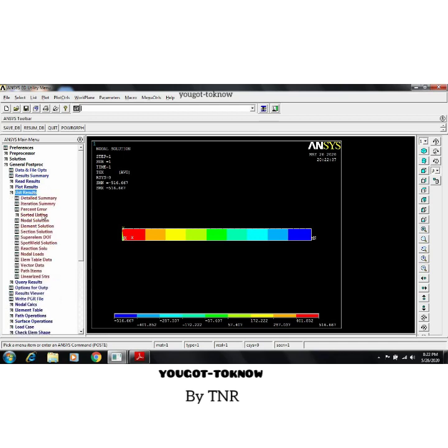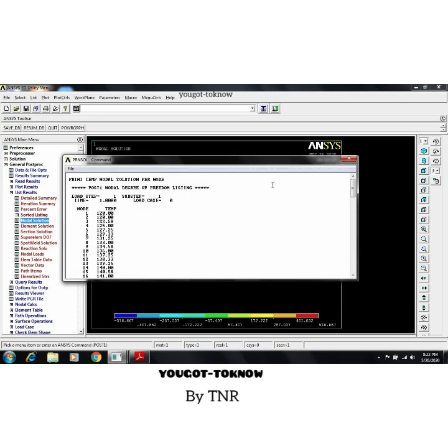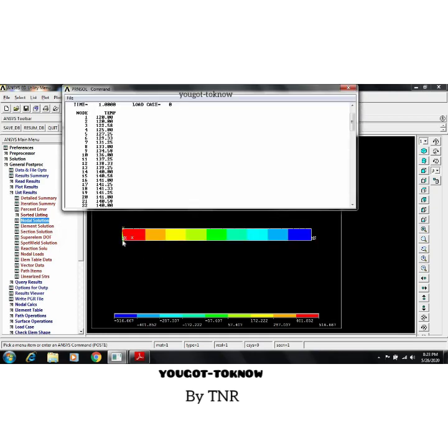List results. Now in list results, nodal solution. Now go to DOF, nodal temperature. Just click here. Now see here, it is giving the values. In node numbers 1 and 2, what happened? Generally in the problem, this is the first node, because while creating your continuum itself, you have created 1 and 2. To create it takes 1, 2, 3, 4. 1, 2 will be over here itself. For that purpose, leave 1, 2. Now count from this 32. So if you count from this 32, that is your 34.